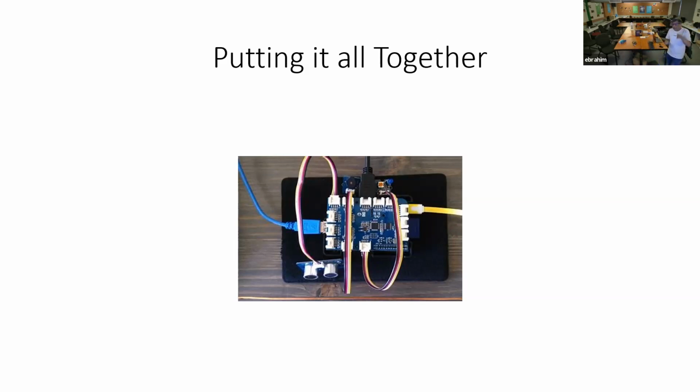That sensor is continuously monitoring the humidity level at that particular point on your windscreen. If it starts raining heavily, it's going to send a message again to the controller: the humidity has increased again. It's going to send a message to the actuator, which is your motor, to start working faster. Or the other way around, the sensor picks up that it has stopped raining. The humidity level has dropped. It sends a signal to the microcontroller. The microcontroller analyzes that data with the software that you have written, determines it has fallen below a certain level, and sends a message to the actuator to stop working.